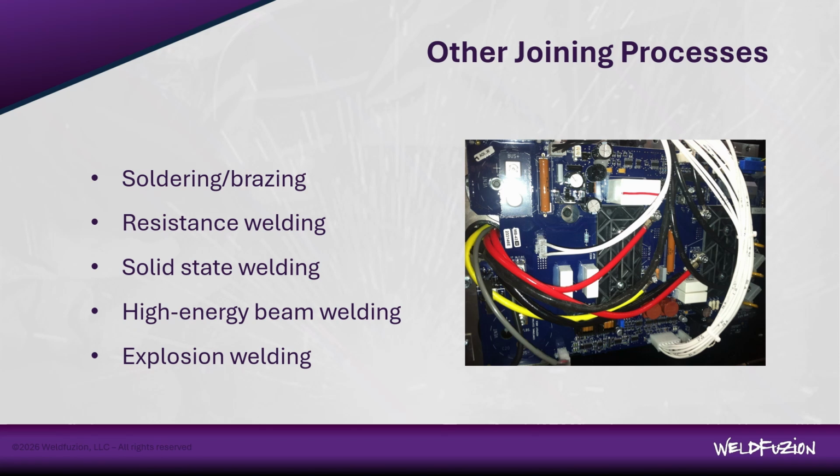As you get into some of these, especially laser, explosion welding, solid state welding, it changes the game a little bit, right? These systems cost more money. If it's the only option, it's the only option, right? And that's the best choice. But in the other case, we don't want to start out with a laser when we really need a stick electrode, right? So that's kind of where I'm coming from there.